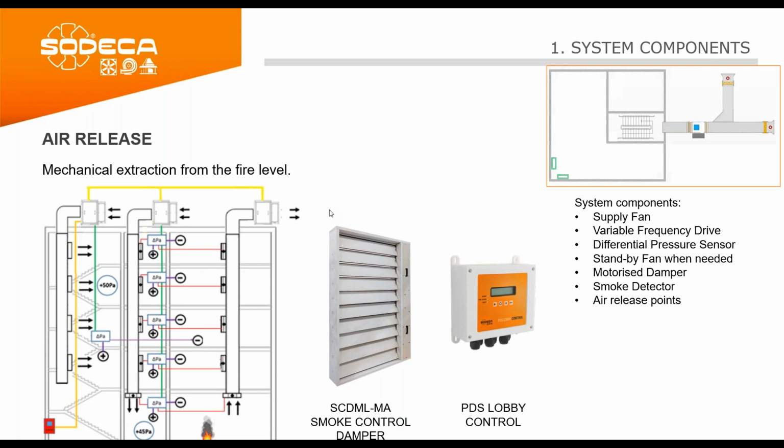And finally, the third option is a vertical shaft connected to an extraction fan, and again with multi-compartment smoke control dampers at every level, and again only opens the smoke damper at the fire level. In this case, the dimension or the area of the duct can be smaller than the one in the previous with the natural vertical shaft.